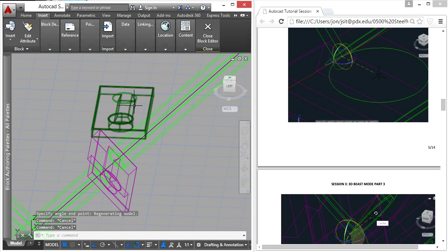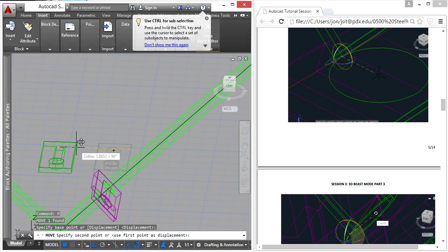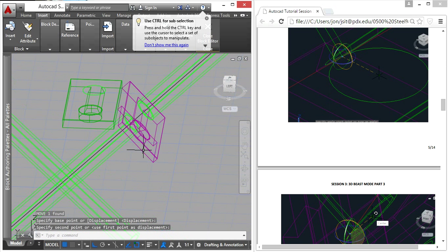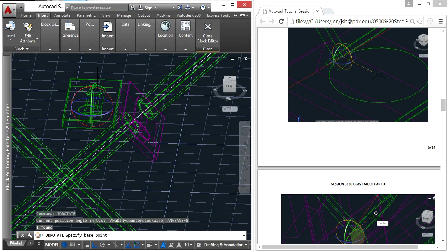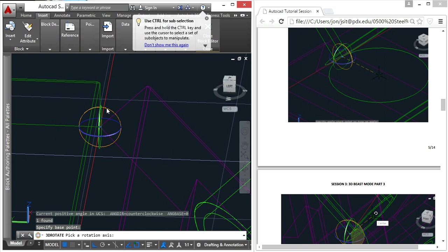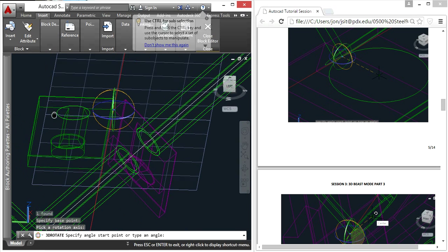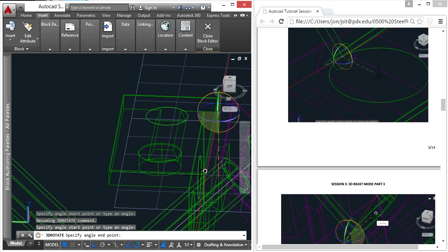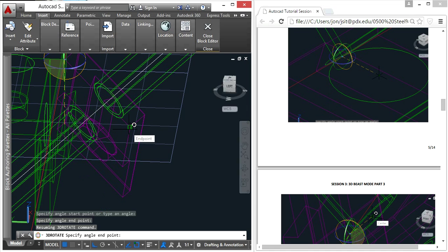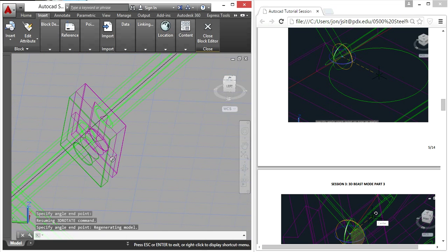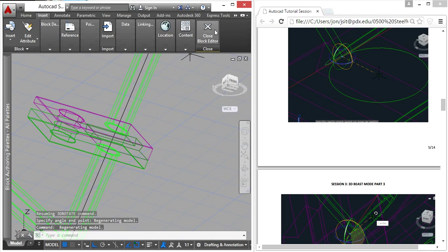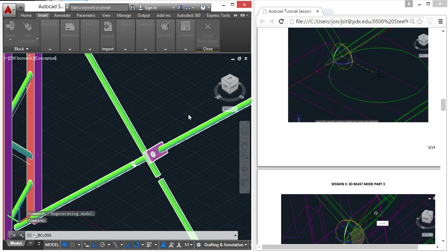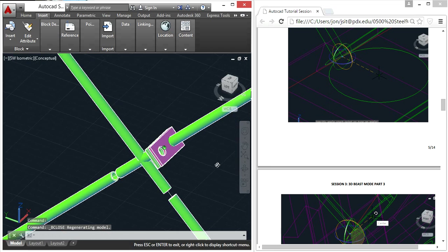It should be facing the exact opposite way, actually, from the way that it's facing. So let's move this corner to that corner. I know these two are supposed to fit together. I'm going to type 3D rotate, click on that, choose the red ring. Let's try to select this corner and go to that corner. Now look at that, they are together. So if we close this and save, look at that beast. Oh yeah.